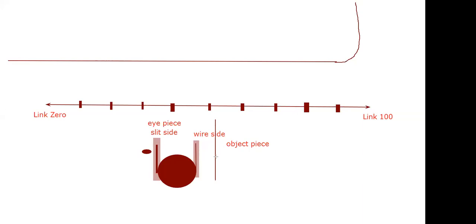After this, from where the ranging rod is placed to link 0, you only have to take one measurement, just one measurement. It saves time. Although the explanation took a longer time, it is very easy to do. Similarly, you will come to link 80, you will place the magnetic compass on your palm and make sure it stays absolutely straight. If you have an elevated surface, a table or a tripod, it is better, but we do not have small tripods for that, so we consider using it on our palms.